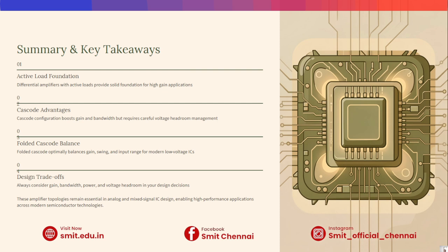Finally, we come to the summary. So, to summarize, differential amplifiers with active loads form the foundation for high gain designs. Cascode amplifiers boost gain and bandwidth but require careful headroom management. Folded cascodes balance gain, swing, and input range, making them ideal for modern low voltage ICs.